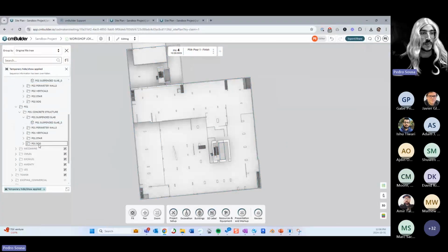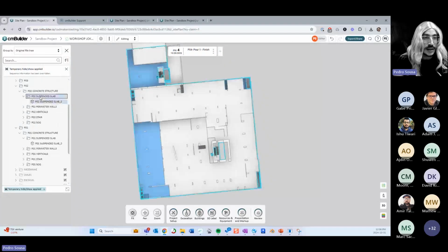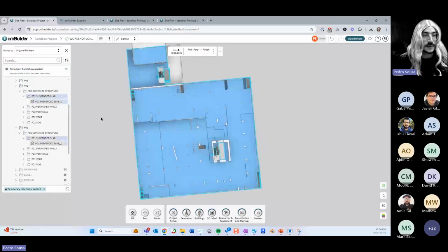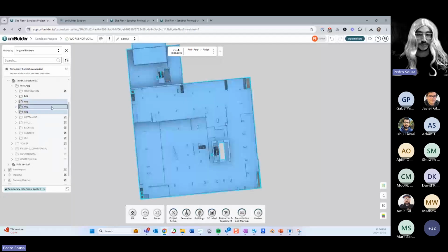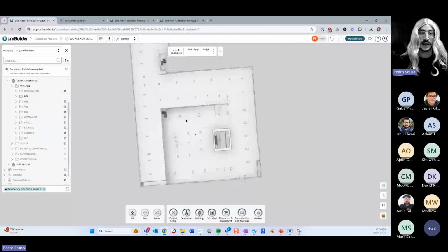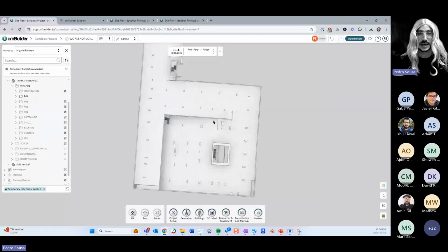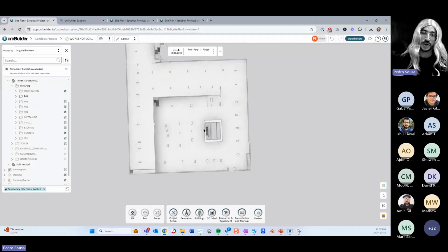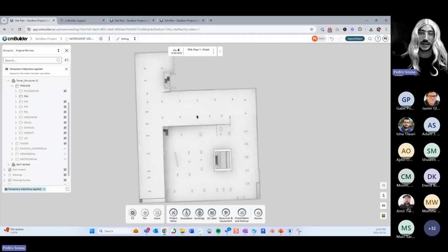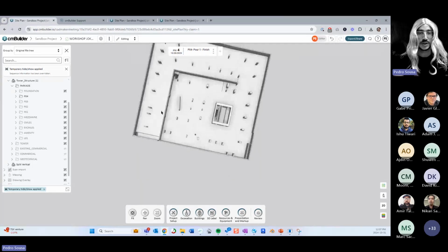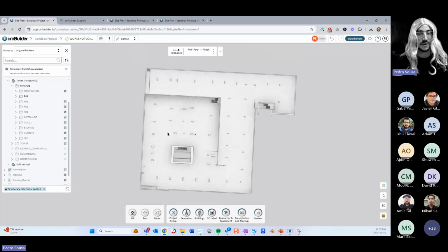Okay, so let's go ahead and also check, starting with our P4. I want to create pour breaks where I want to slice this model here, and then have two slabs over here, isolate this area and isolate this area. So I'm gonna do one pour break first so you can see how it works.